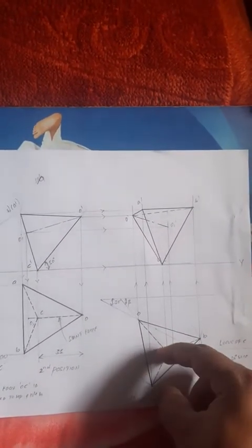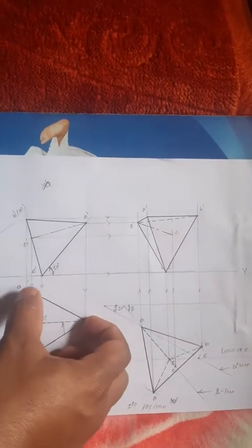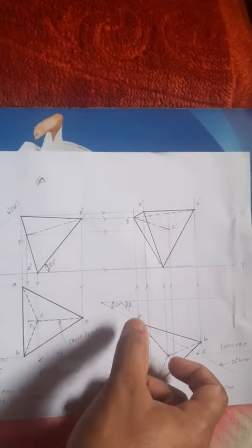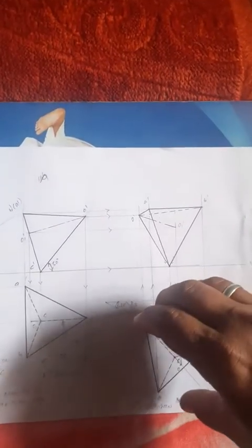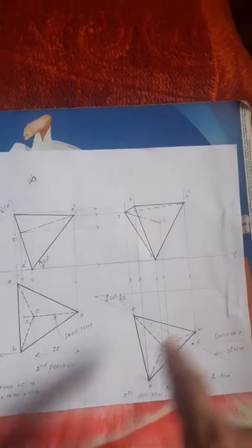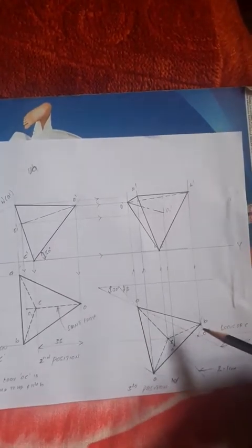C is the center, then draw an arc on either side. Then O is the center, OA is equal to OB. O is the center, draw one more arc. Now you just rotate the solid on the beta degree. Now A will come this side corner, B will come this side. Then just replace this, then draw the lines, O to A to B, B to O, right? That completes the third position, top view.